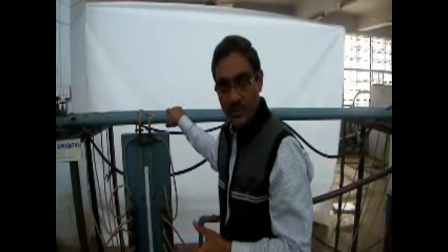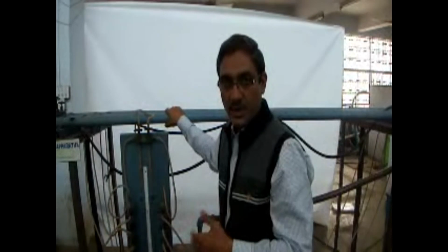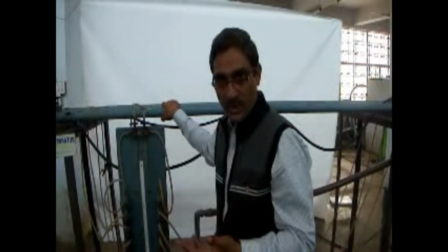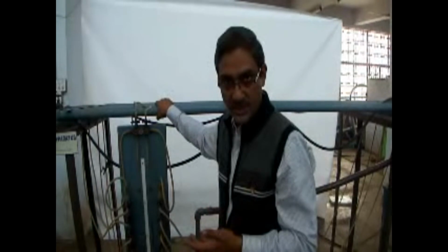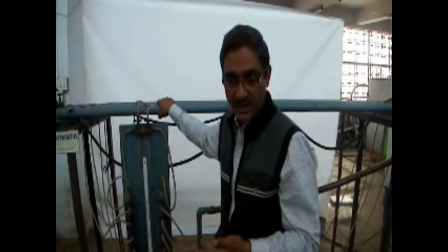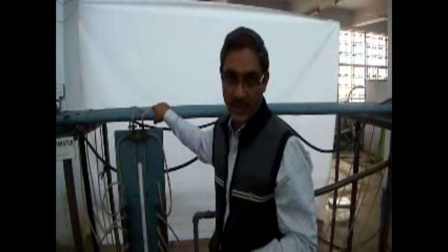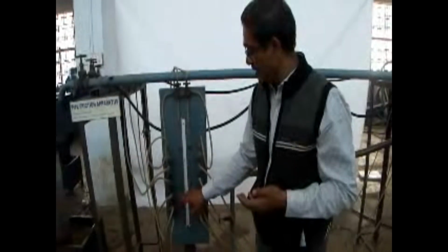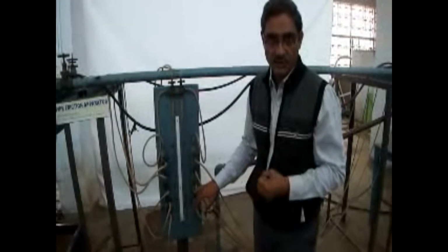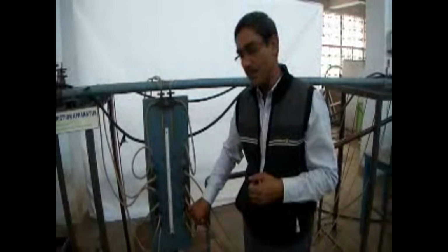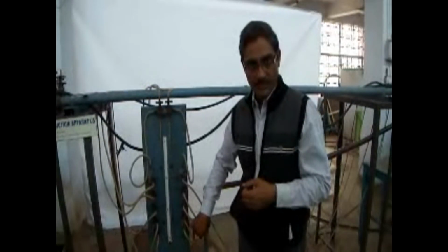So with this observation, you can use the discharge to find out the friction factor of this steel pipe for different discharge conditions, and based on that you can answer whether the friction factor changes with respect to discharge or pipe size, or what the friction factor is. That is measured or estimated using the head difference, the head loss due to friction, which is also called major head loss in the pipe system. Thank you.